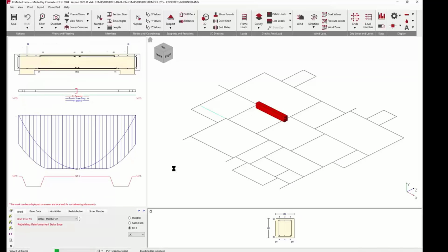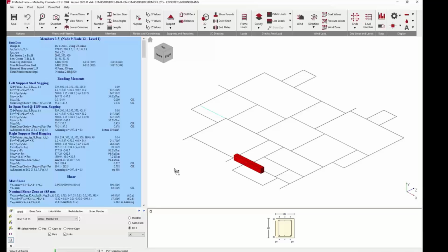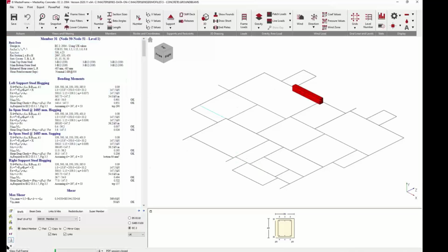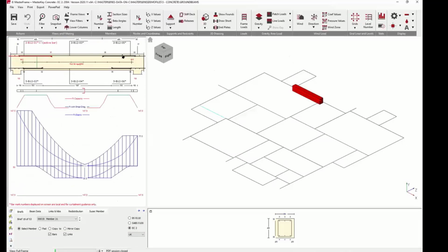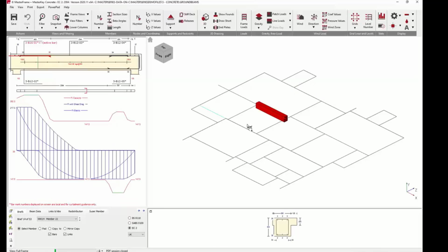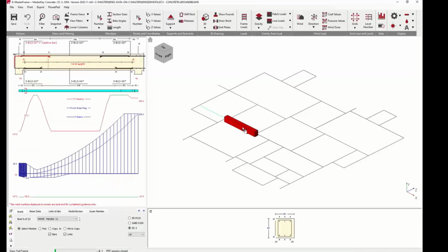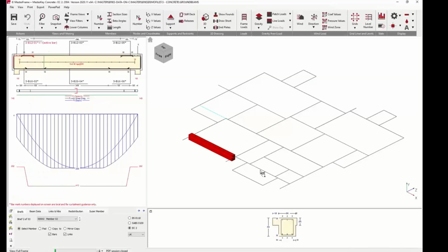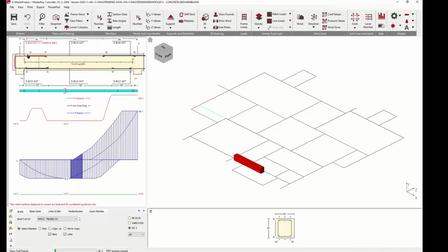And it runs along. And one of the things you find with ground beams is the spans can be quite short between piles, because it's domestic, between locations. So let's have a look, and you'll see that we've got these 12s and 12s with the 12s lapped. So there's a lot of lapping going on in these short-ish spans. And one of the things we've found is that rather than doing your traditional mid-span support, there's another method of curtailing that is actually a lot more efficient in ground beams.